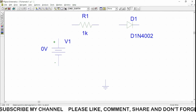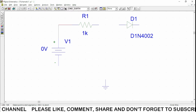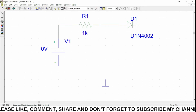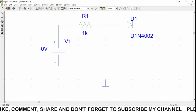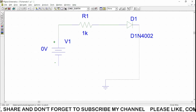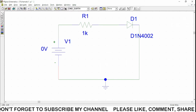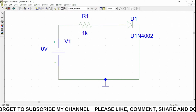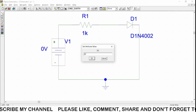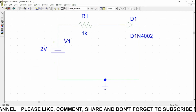Control W is the option to connect. VCC's plus terminal goes to resistance R1's one terminal. R1's other terminal is to be connected to diode D1's anode, and the cathode is connected to ground. This ground is connected to the negative of the battery. Okay. Now I am going to set the voltage to a maximum of 2 volt. Okay. So we are done with the circuit diagram.